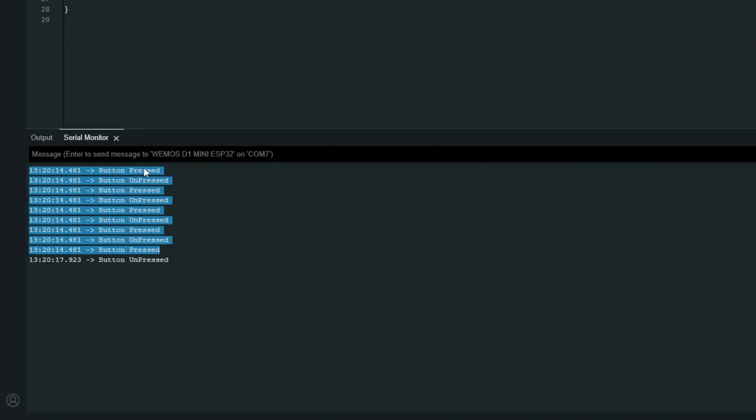And we can see that on the scope when we put this on the oscilloscope. It's bouncing over and over again, and it looks like we have timestamps here for when these serial messages arrived. It looks like they're all within 10 milliseconds of each other, which means it's a very quick bounce over and over again.